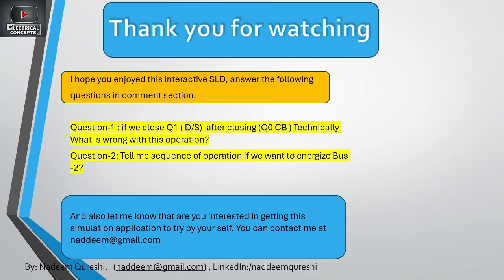Kindly answer the following questions in the comment section. Question number 1, which I have discussed: if we close the Q1 disconnector switch after closing the Q0 circuit breaker, technically what is wrong with this operation? Question number 2, tell me the sequence of operation if we want to energize bus 2 instead of bus 1. And also let me know if you are interested in getting this simulation application to try by yourself. You can contact me at this given address.